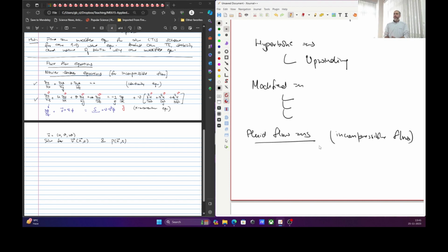So first, what we did was we tried to get away with this using the vorticity stream function approach. We said that let's get rid of pressure altogether. So we ran away from that problem by talking about the vorticity stream function approach, and there we learned how to derive the vorticity equation. And interestingly, vorticity equation was also like the transport equation, right? It had the same form as it had a convection term where the phi got replaced with omega.